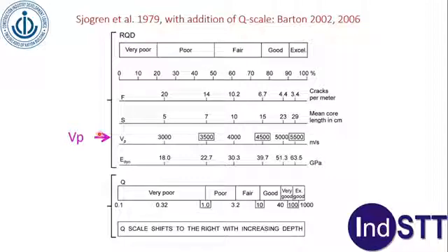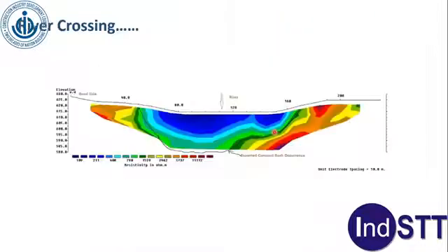This is detection of a sewer pipe, an underground sewer pipe. It can be done across flowing rivers. So this is one of the major applications for trenchless operation. Very quick investigation across rivers. This was from Karnali. This was the river portion, and this was the expected compact rock occurrence, which was interpreted by gradient of resistivity. This, of course, was cross-checked afterwards with the drilling on the location suggested by us.